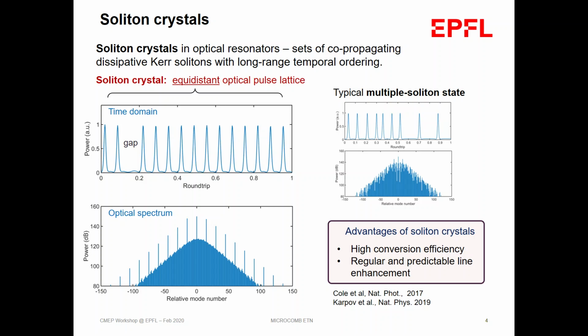But on Monday, we learned that the ring cannot be really small because of the bending losses. So you will lose everything. You have large losses, and not only this, it's hard in fabrication terms, and it's really painful. So what people proposed is to generate a so-called soliton crystal. You generate solitons which stand equidistantly inside your resonator, and effectively your FSR, the free spectral range, changes.